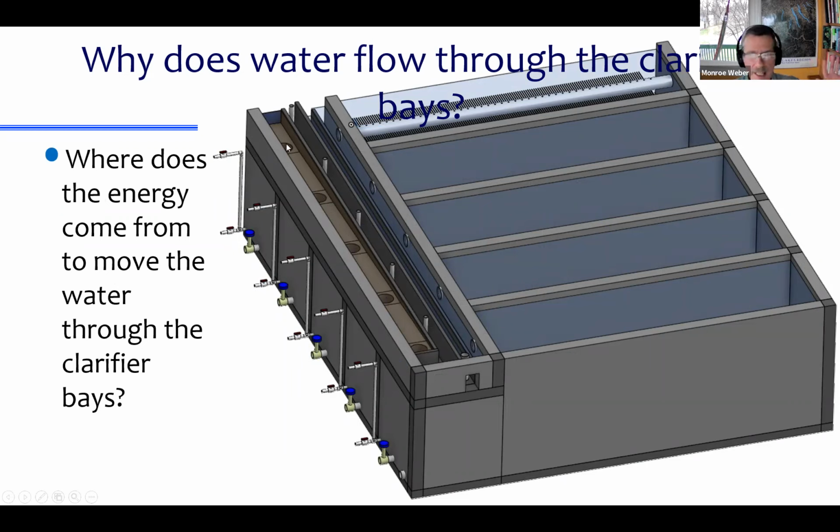inlet manifolds. It then goes down through the diffusers, around the jet reverser, up through the flock filter, up through the plate settlers, and then into this outlet manifold along the top of the clarifier, out this port, and then it's into this little channel, and that channel has a weir, and it flows over that weir and drops into a channel where it then exits and somehow magically gets to the filters. So the water enters in this channel, and as far as the clarifier is concerned, it's exiting again in the channel that's right next to the clarifier bays.